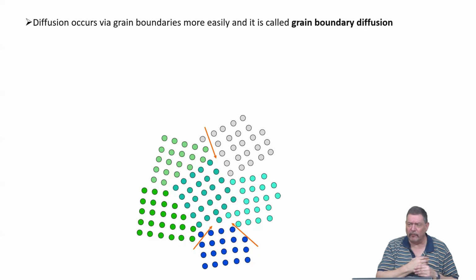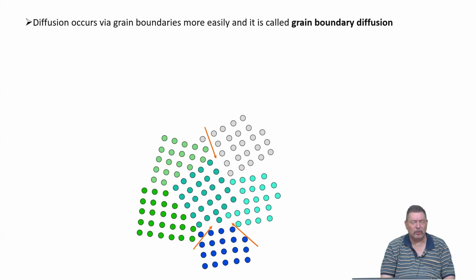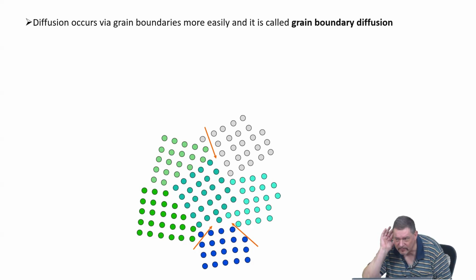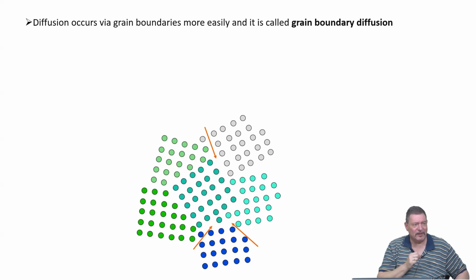If you should now venture a guess thinking about different grain boundaries, and I think all of you know that there are different types of grain boundaries, what would you think? Which grain boundary types show rather fast and which grain boundary types show rather low diffusivities? Are they fast or slow? Fast. Very good. Yes, exactly correct. And then the low angle grain boundaries are rather slow diffusing pathways.